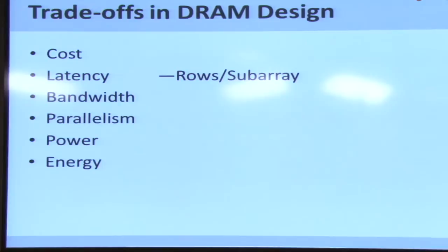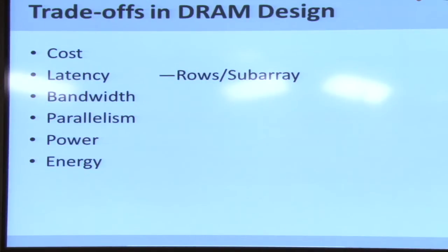Okay. The delay matching would be very hard, I believe. So I think you're giving the answer speed, right? Which means if I have to send 64 bits at the same time, that means I have to build faster DRAM, right? And today with the technology that we have, it won't be possible for us to build faster DRAM, right? In fact, DRAM internally operates at 4 times lower frequency than the bus, right?